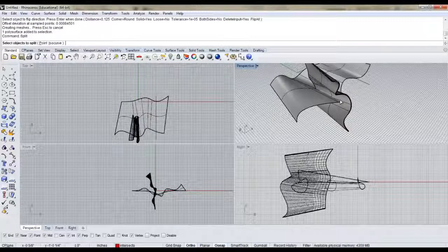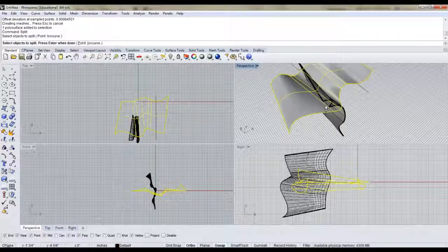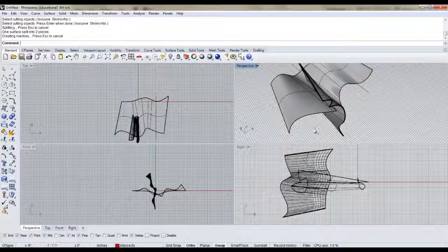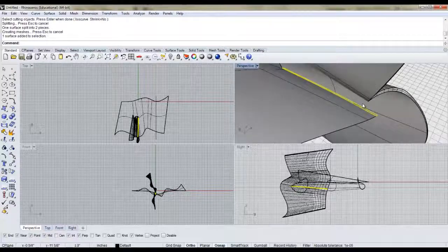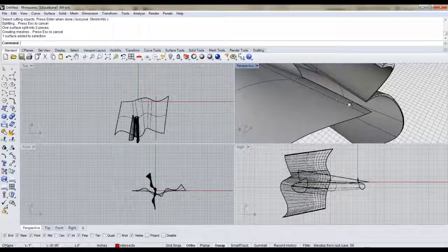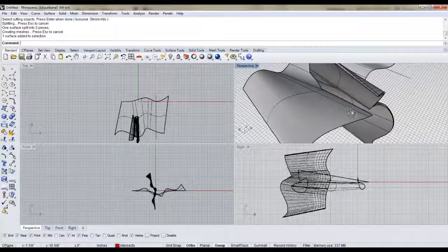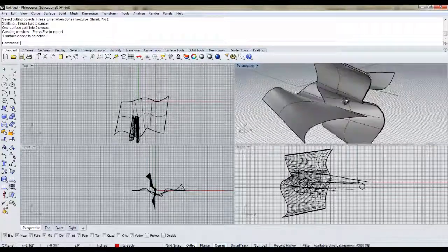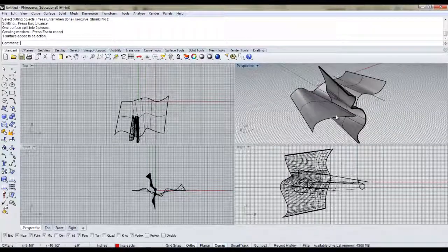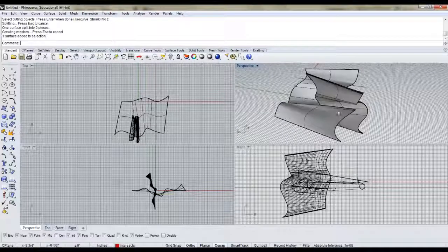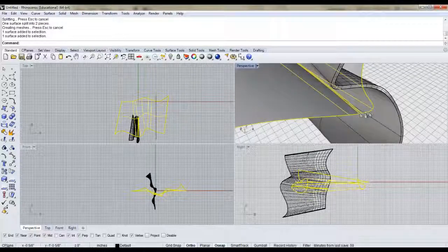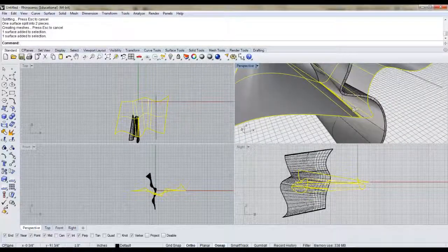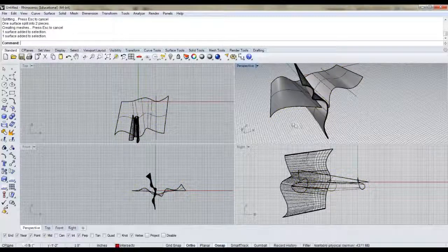So now if you type in split, and I split this first surface by the second, what we'll get is the area where they're overlapped, and this will read clearly as a line in the Make2D. Sometimes the intersects are complicated, especially with curved surfaces, and that's why when you try to make a Make2D, the intersection won't be legible. However, this is a permanent manipulation to this surface, so that this region is definitely no longer part of that initial one, so it's damaging it.